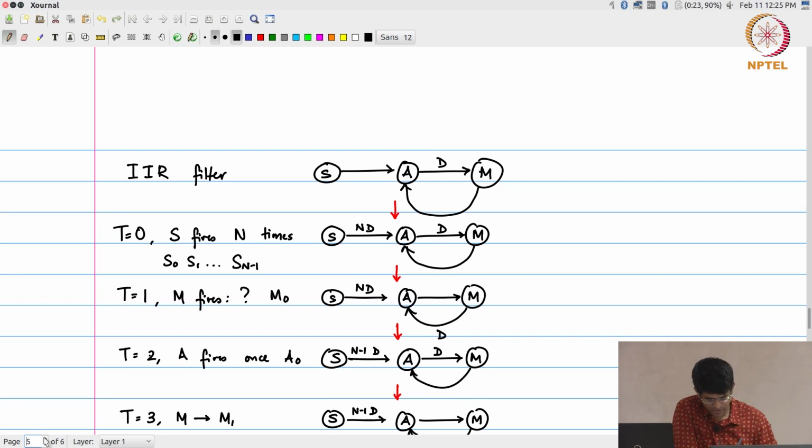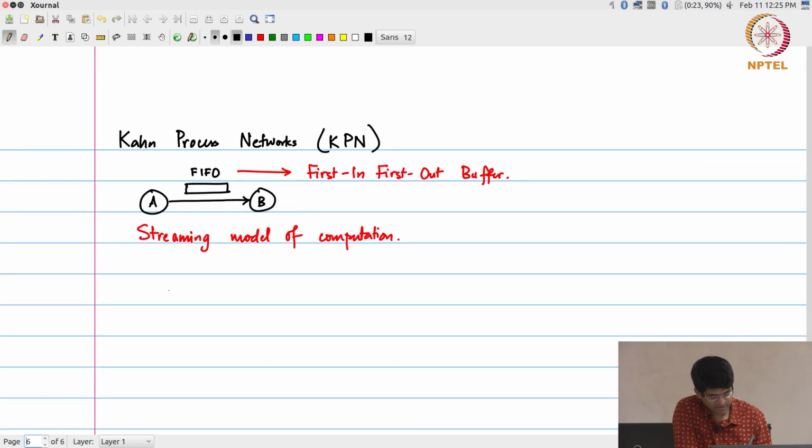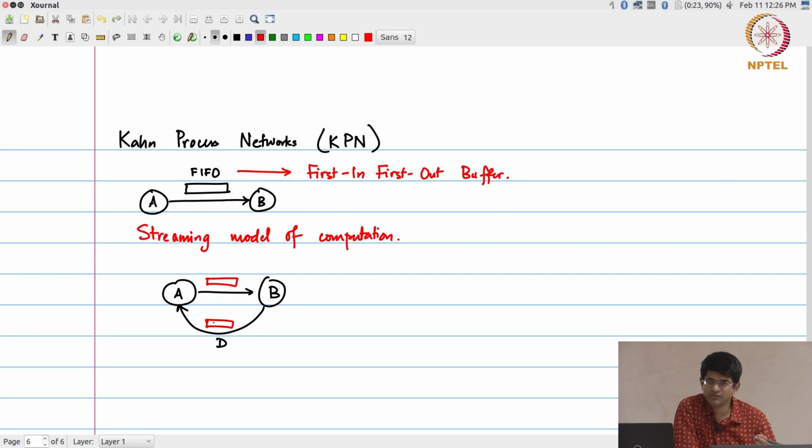Keep in mind over here that if I, for example, have something of this sort, I need to have at least one delay element over there, one token, but the FIFOs themselves, I could have FIFOs on both edges. That's just an implementation issue. The important point to keep in mind is, just because I have drawn two FIFOs over here, one on each edge, doesn't necessarily mean that there is actually data sitting in any of them.